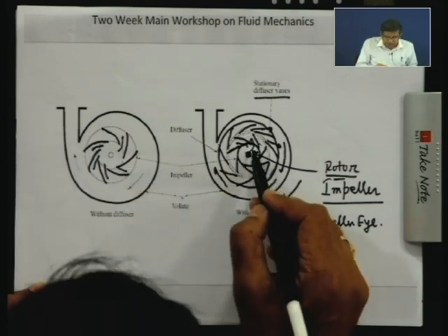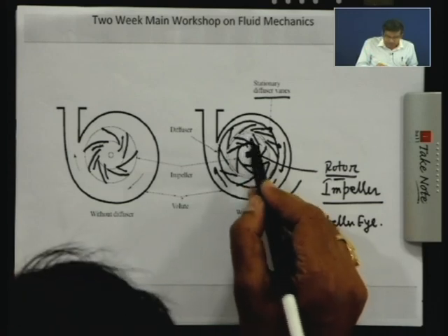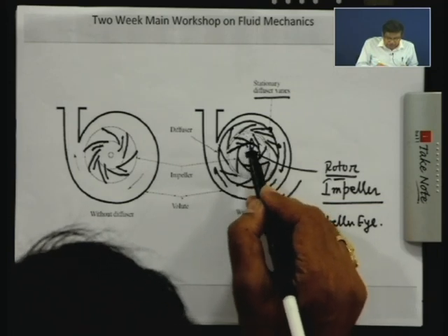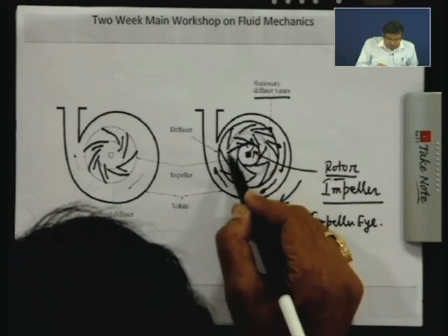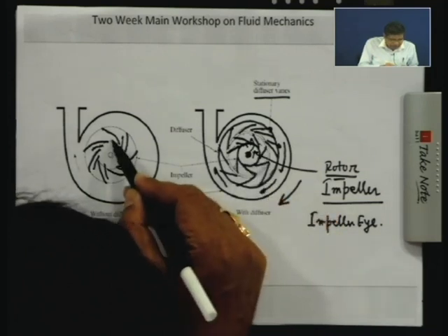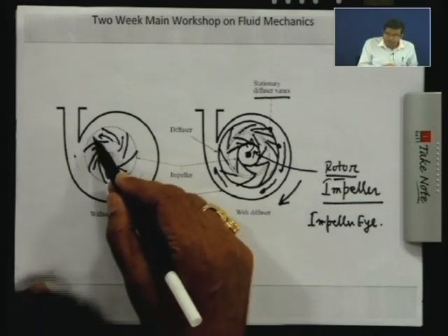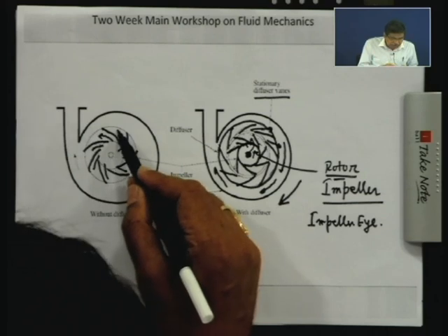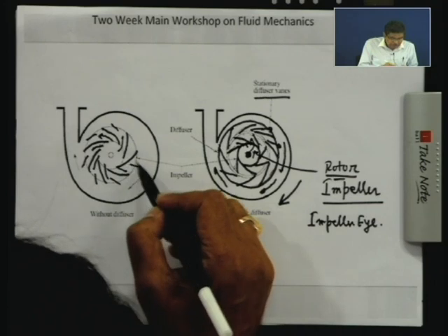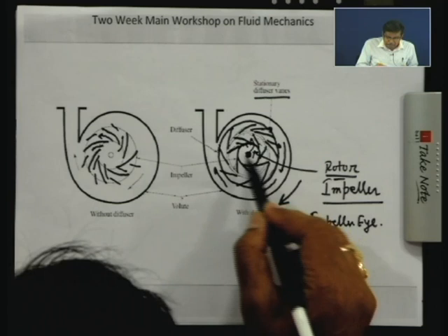Obviously, a pump has to be radially outward flow to gain its pressure; its inlet radius should be lower than the outlet radius. So, therefore, it is a radially outward flow, and while flowing through these rotating impeller blade passages, the section is diverging, that means its relative velocity is decreased and as a consequence pressure is increased. So, therefore, when it comes out from the impeller blade passages, it has increased kinetic energy because of the impulse action of this impeller.